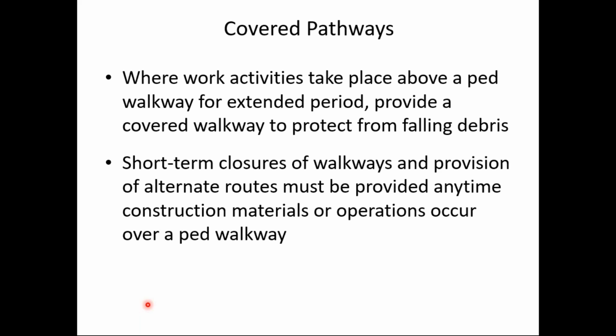In some cases, we may need to have covered pathways or canopies. If you have work activities taking place above a sidewalk or walkway for an extended period of time, you need to provide some sort of protection from falling objects.